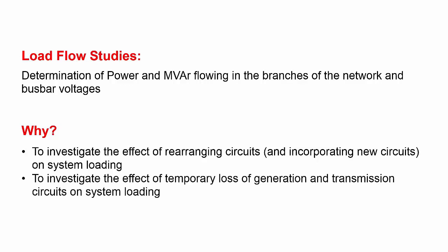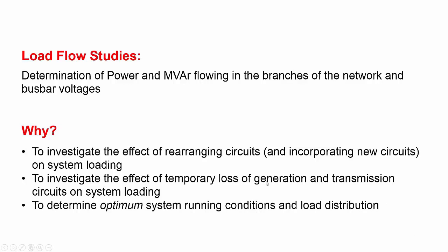Also, this would help to investigate the effect of loss of generation or loss of transmission links, if you're taking a transmission link out for maintenance or if there is a fault. So basically, it will help the power engineer to decide on the security of the system under various scenarios. And more, we use power flow analysis to determine optimum system operating conditions. Optimum, I put it in italics here. It means the most economical way of operating the system.